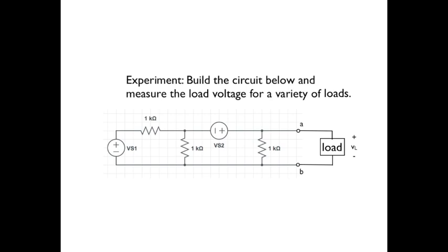In this lesson titled Experimental Investigation of Thevenin's Theorem, we plan to do exactly what the title says. Previously, we've examined Thevenin equivalent circuits and Thevenin's theorem from an analytical point of view, you might say with pencil and paper, and we showed how a linear circuit could be replaced by one voltage source and one resistor, that is the Thevenin equivalent, and that the two would be equivalent from the perspective of what was connected to the output terminals of both.